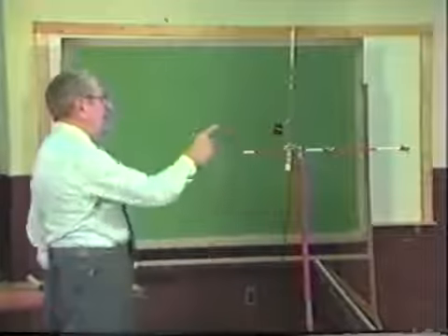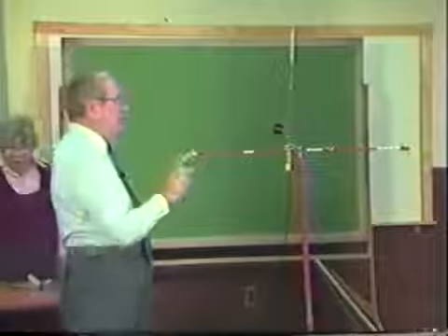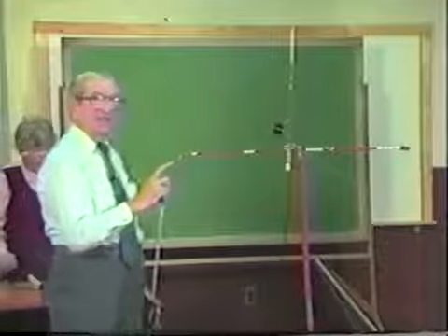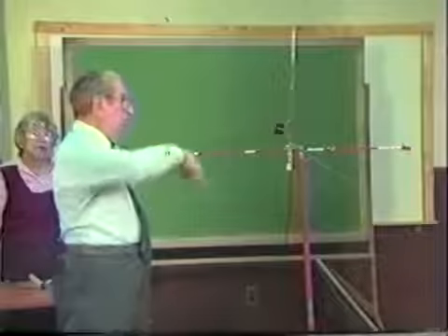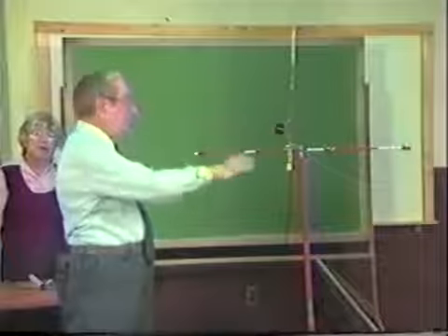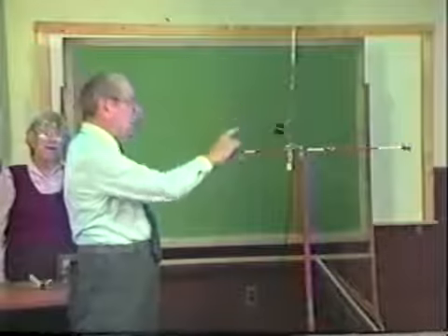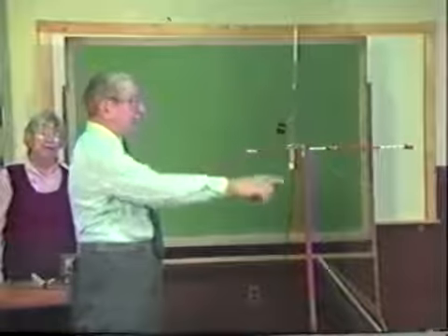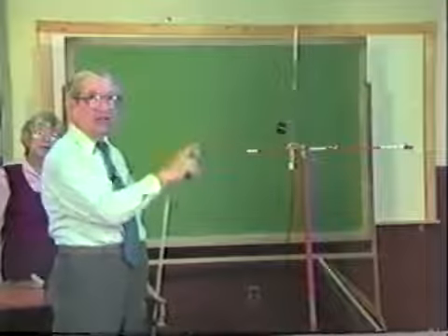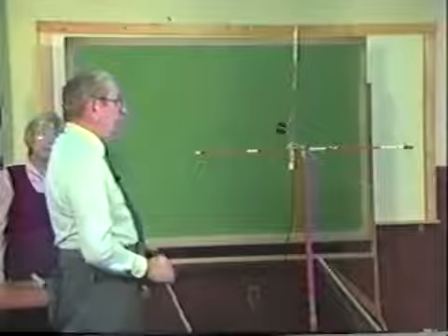So that now you don't have a vertical type of antenna. The radiation from this antenna will not be the same as we had before when we had a true vertical antenna with our donut all around it. Here we have a distorted quarter wave antenna, where the plane of each one of these legs is almost at 90 degrees angle to each other, so that you'll have cancellation, you'll have various things happen to it.